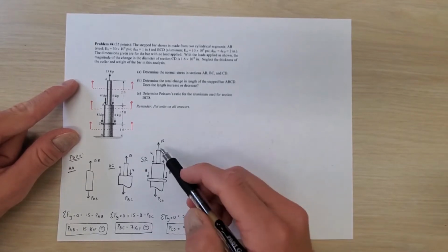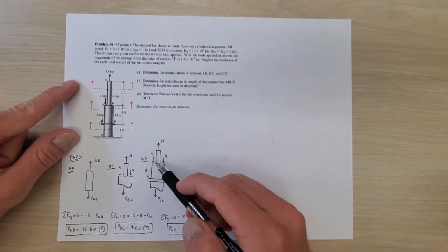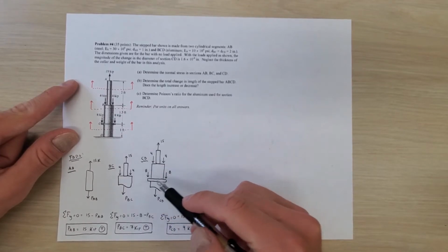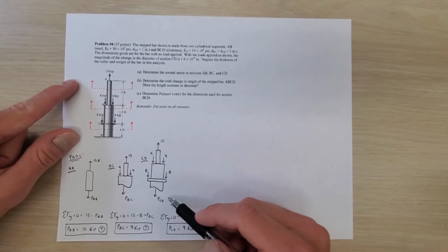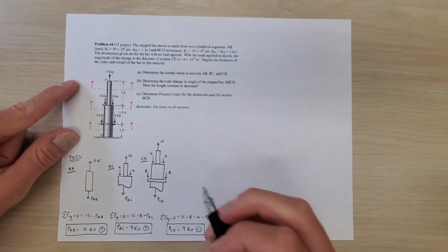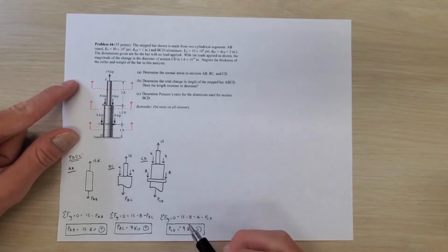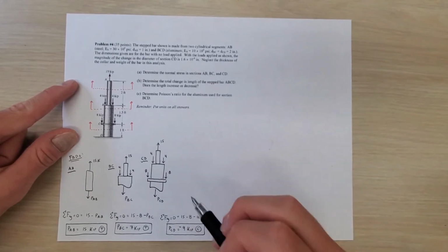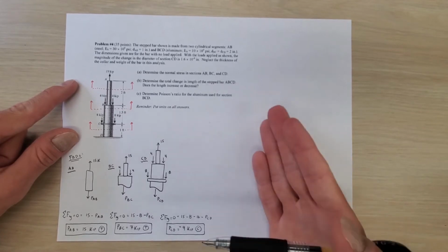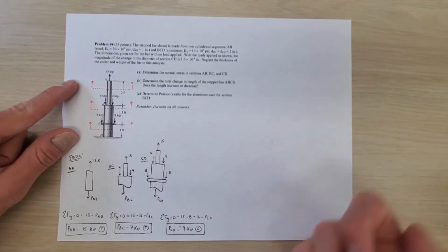When we look at this section cut over here, section CD, we'll see that the sum of the forces in the Y is going to be 15 up, minus the 2 4s going down, minus these 2 8-kip forces going down here, and minus PCD. So you'll see we've got all of that in our equation right here, and we actually will get a negative answer for PCD, which means that it is in compression. So that's why I put a little C right there, and if we want to, we can put a negative, but to me, I don't really care when I look at the answers to this. As long as you've got this circle here, I know whether your answer means tension or compression.